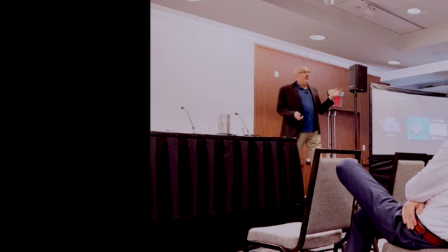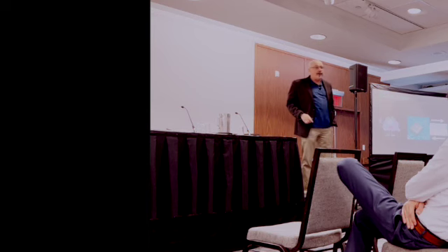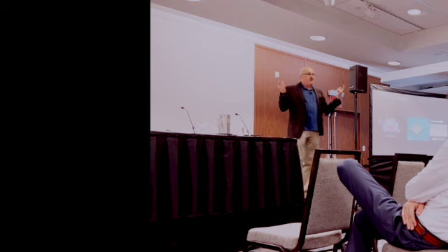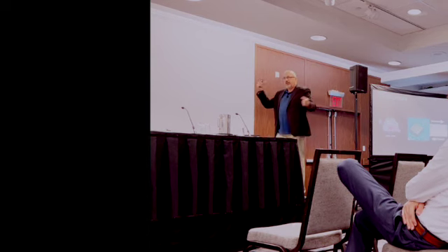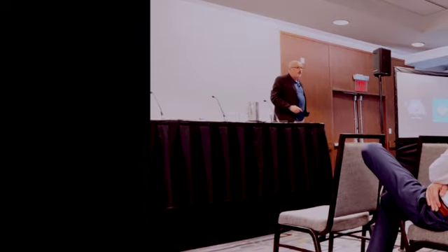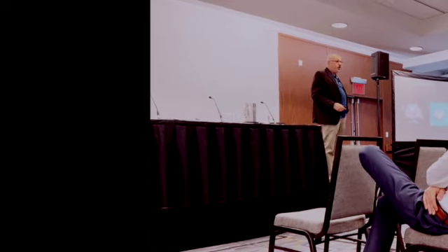So what can't we do? We can't do grouping. We can't do, let's just make this side of the room react to a sensor and the other side of the room not react to it. Can't do any of that. So what you need to do any of that is you need 2 brains, one at the controller and one at the load. And those brains will talk to each other, and they will get a signal that says, do something. And each fixture can independently do what it wants to do, or it's being told to do. And then commissioning is the act of explaining to the controller what you want things to do.